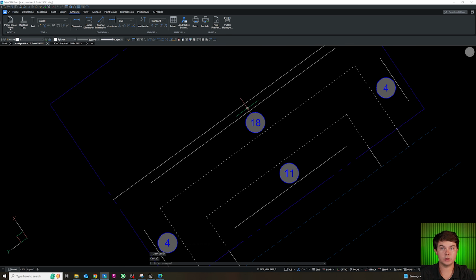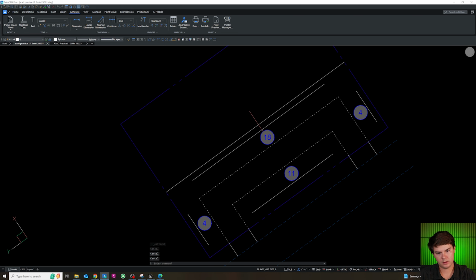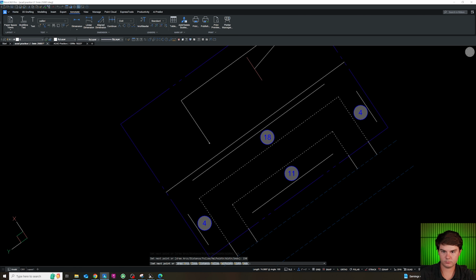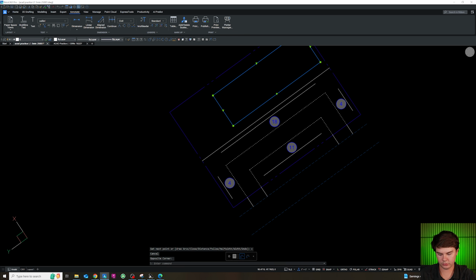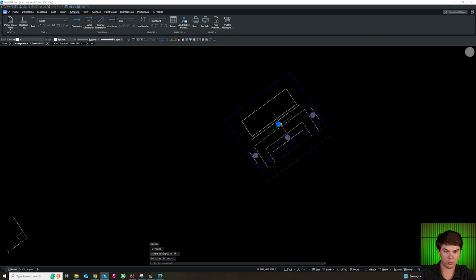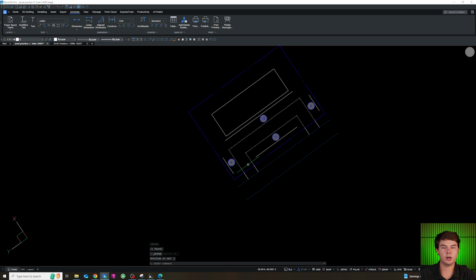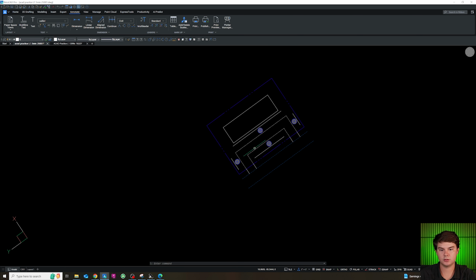And our 6 feet for the building sidewalk. Now our building is going to be 50 feet by 150 feet. And then to close, you can hit C space and it'll close your rectangle for you. I'm going to drag this by the midpoint to this midpoint. Now our building is here. And now we've got our drive aisle, our parking, our building, everything wireframed in so we know how it fits. Thanks for watching.